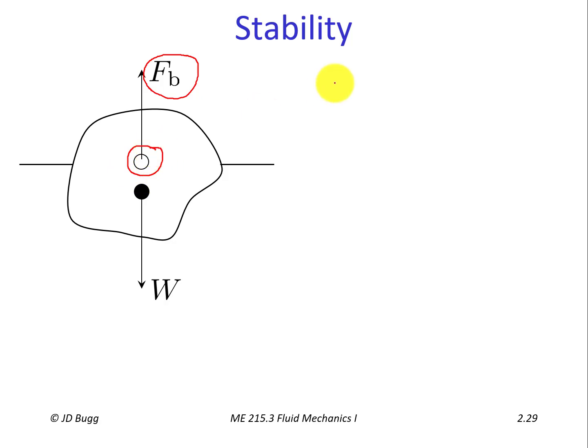Now, how would we figure out where that center of pressure would be? Well, we would have to calculate the buoyancy force as we've indicated on the previous slides. We would actually also need to calculate the moment that this fluid exerts around the origin of our coordinate system, and then take that moment, divide by the buoyancy force in order to locate this center of pressure.